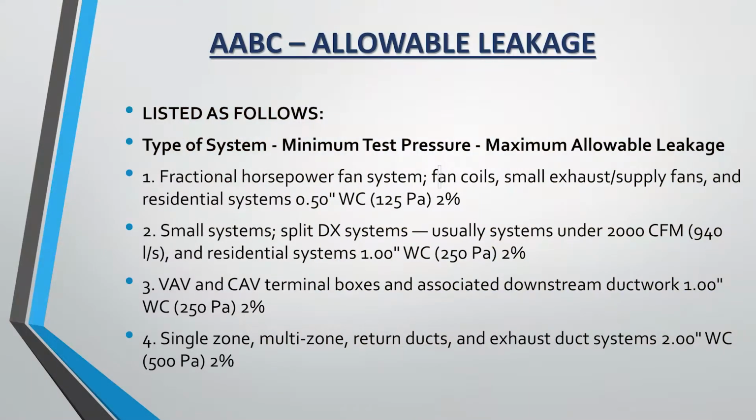So next thing you know, they were taking little sections of duct. I mean, we're talking about 3 sections, 4 foot or maybe 5 foot. So we're talking about 15 foot of duct. They couldn't get it sealed. Just, you know, generally putting it in, slapping dope on it, away they go. Miserable. And that compromised their efficiency going down the road with all their VRF units, thinking, well, we got this thing licked. We're going to have a great system. No leakage above the ceiling. And yeah, talk about 400 CFM on a 1-ton unit or 500. You're leaking 15%, 18%. You got 30 of them. You do the math. That's a lot of air you're not using.